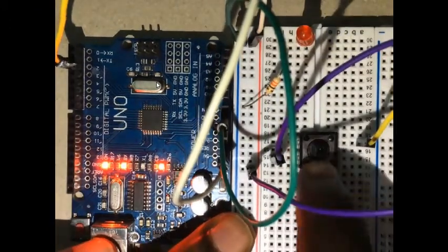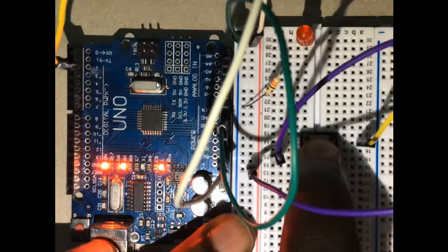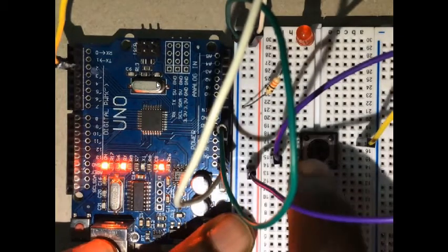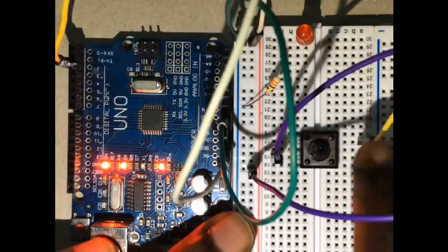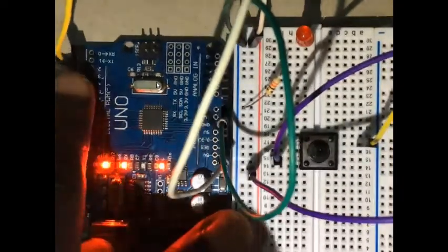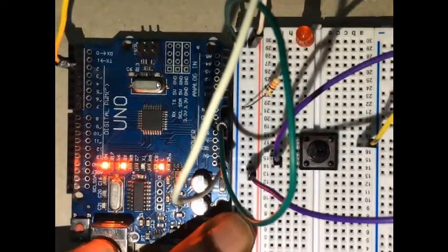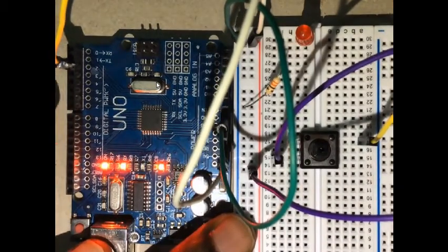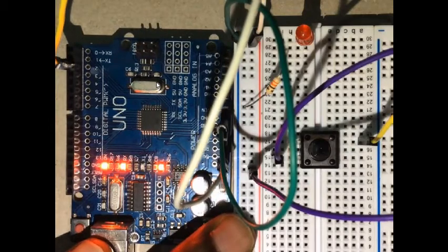we have connected that side of the button to pin 2. That means that when we press this button, it allows a 5-volt voltage to flow into the yellow wire and back into our digital pin 2. That means that the voltage level on that digital pin 2 will be 5 volts. Do you understand? Will be 5 volts.